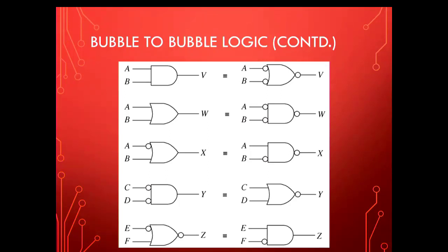You're adding 3 inverters, meaning you need 3 inverters. So you would need 3 wires to connect the input of those inverters and those outputs. So more wires, more delay, a bigger circuit, and then the delay between them also. So you're adding a little bit of complexity here. But sometimes we have to do it. We don't have any other option.